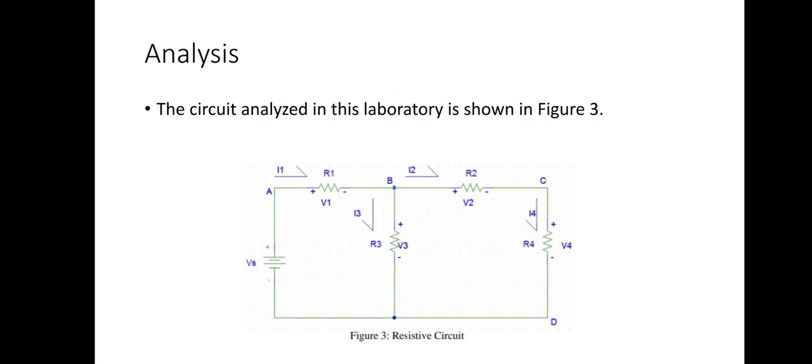In order to simplify the KVL equations, the polarities should be assigned to satisfy the passive sign convention whenever possible. Now, in the case of KCL, the passive sign convention deals with the direction of the currents with respect to the node. Currents entering the node must have opposite signs to those exiting the node.